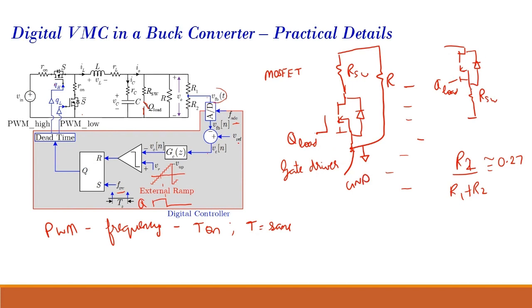If it was in this case, we'd have to boost it to this potential and then apply the gate signal. So to simplify, we just apply the signal with respect to the ground, and we can just use a simple low side gate driver. Whereas if you recall, to implement this, here also we require a gate driver.